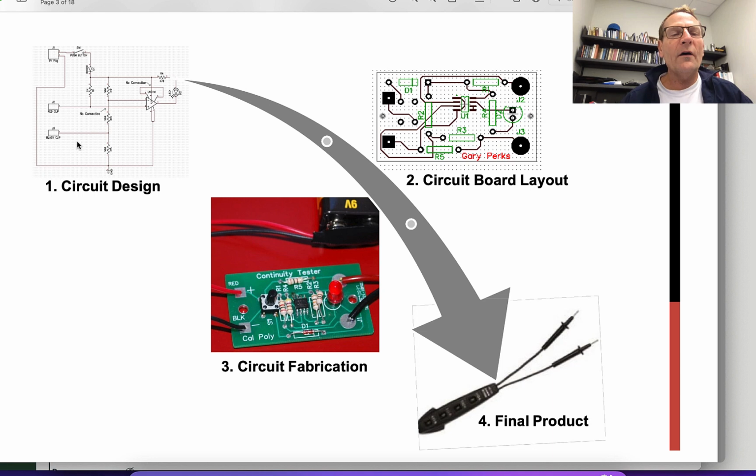We will walk through creating the schematic, the electrical schematic, which is a series of electrical symbols representing the actual components such as resistors and switches and LEDs, etc. You will lay those out on a circuit board layout, which is basically the two-dimensional CAD illustration that represents the locations of all the holes and electrical connection features that will need to be manufactured onto the board.